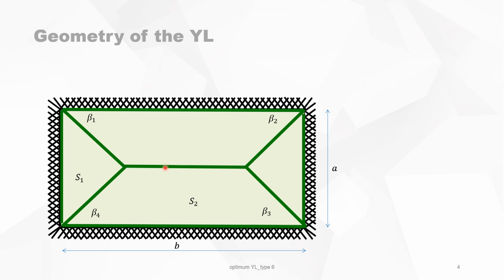This is a good hypothesis if we assume that the reinforcement on the top is equal to the reinforcement on the bottom of the slab, because we are working in an upper bound system and we are working at full yielding of the reinforcement steel.